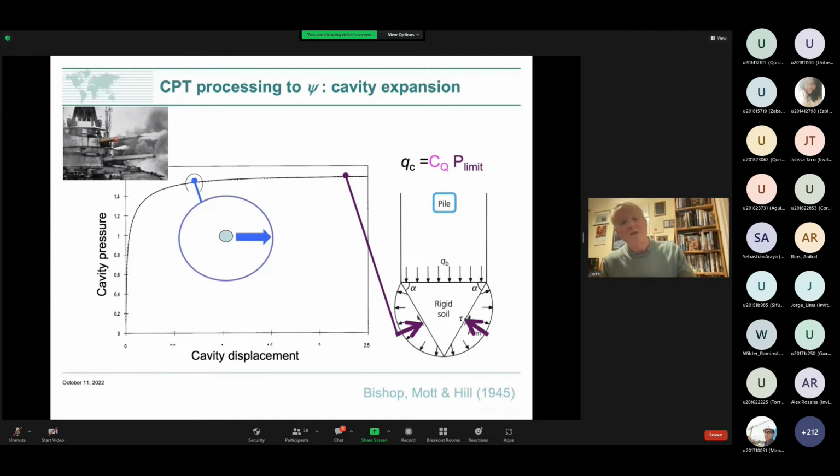And the reason it's called cavity expansion is the cavity was actually the gun barrel. It was a cylindrical cavity. Now, why do we like cavities? Well, the answer is it makes the mathematics very simple because, yes, it's a 3D problem, but we can write everything in terms of radius. So even though it looks 3D, mathematically, it's actually 1D.